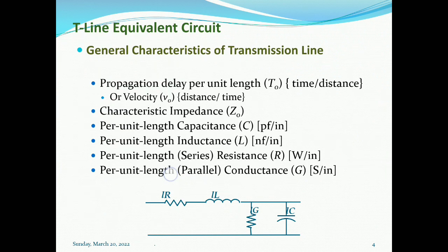Depending upon the cross-sectional area of the conductors, the transmission line will have resistance associated with it. It is denoted as R. What is the capacitance? The transmission line consists of two parallel conductors separated by a dielectric like air. Such parallel conductors separated by an insulating dielectric produce a capacitance, which is also distributed along the length of the conductor. It is denoted by C.